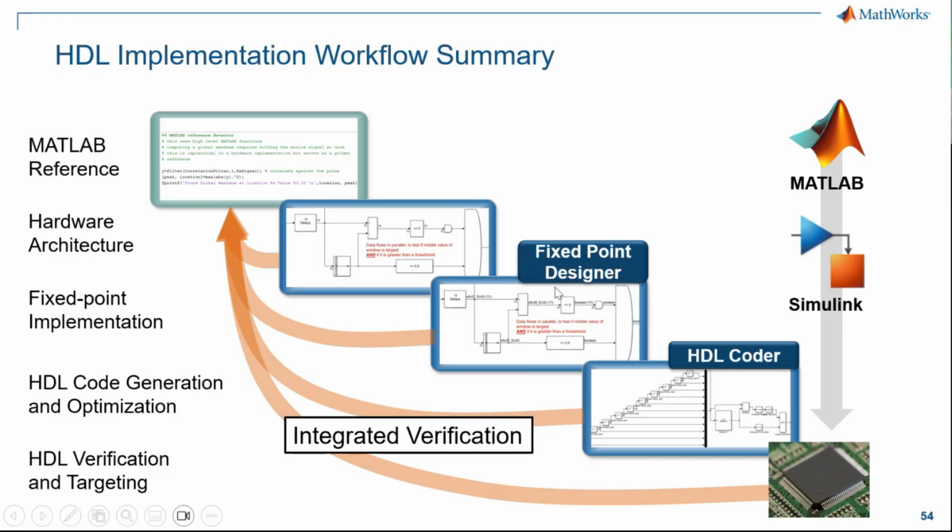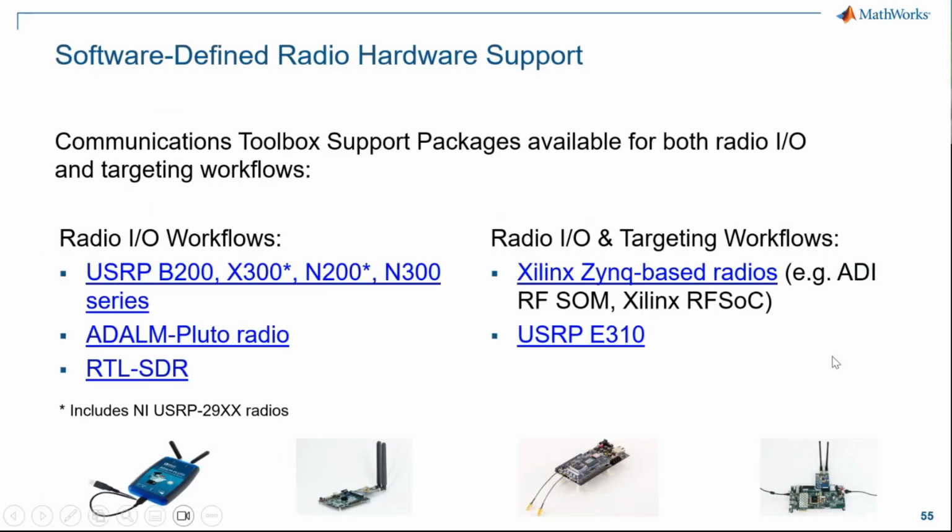It's going to propose some fixed-point configuration that makes sense, and you will be able to optimize with an iteration process that we describe clearly. It's going to generate code. It's going to be very easy to use the scripts, the initial models, to verify that your design is bit accurate, that everything is running as expected. So this is what we are really focusing on, making sure that we can provide an end-to-end solution.